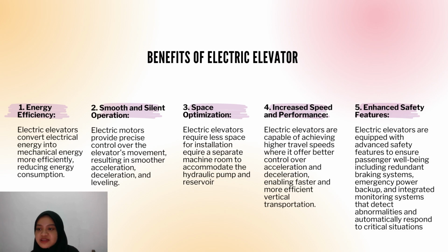The next benefit is increased speed and performance. Electric elevators are capable of achieving higher travel speeds compared to hydraulic elevators. Electric traction systems, such as geared or gearless machines, offer better control over acceleration and deceleration, enabling faster and more efficient vertical transportation, because electric gearless elevators achieve higher travel speeds and shorter travel times.